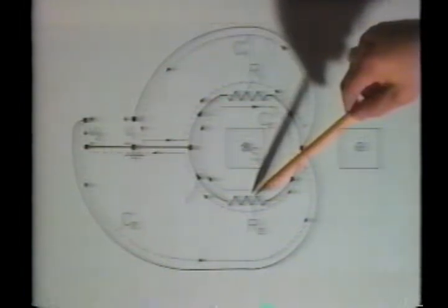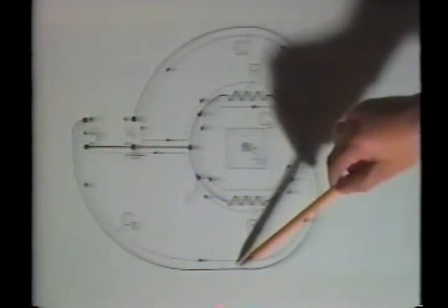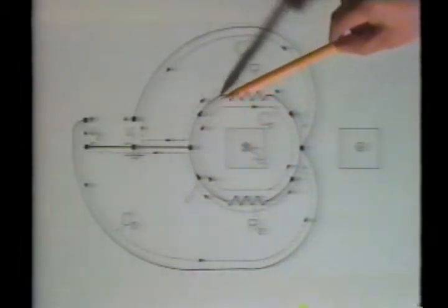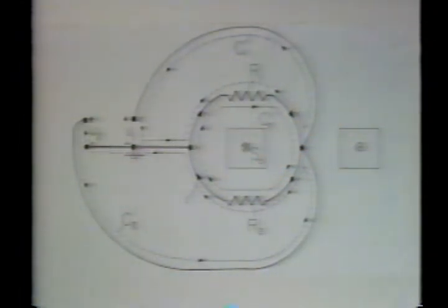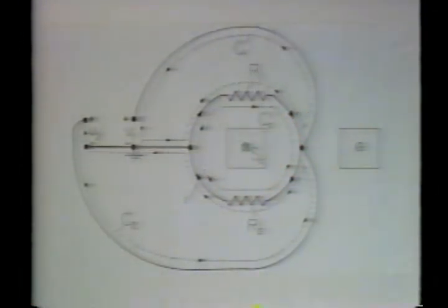Here, the key contour is the path of circulation through the resistors, and the surface cuts through the core. The voltage measured by trace 1 is determined by applying Faraday's integral law to this contour. Because it links a negligible magnetic flux, what is measured is just what is expected, the negative of the current times the resistance R sub 1. The voltage measured by trace 2 follows from this contour. It is the same current, but multiplied by plus R sub 2.